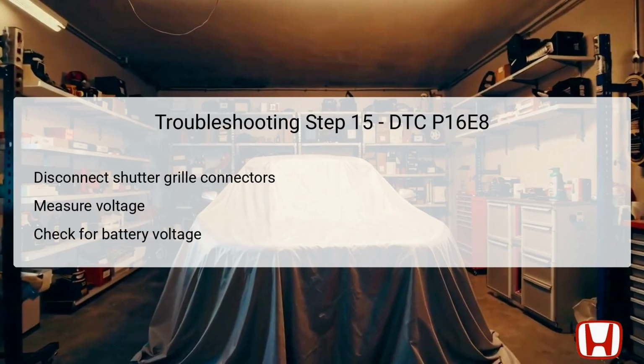If voltage is present, it indicates the circuit is functioning and allows the technician to progress to further detailed diagnostics. Alternatively, the absence of voltage may signify open wiring conditions either along the communication paths or damaged terminals, necessitating repairs as per the findings earlier.